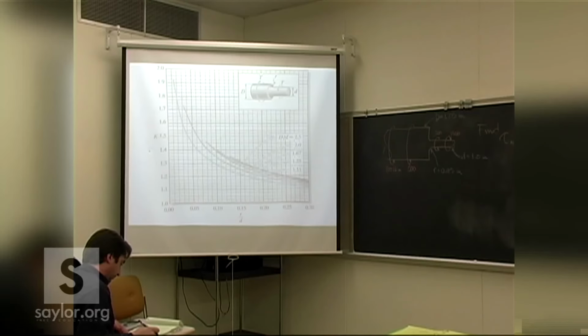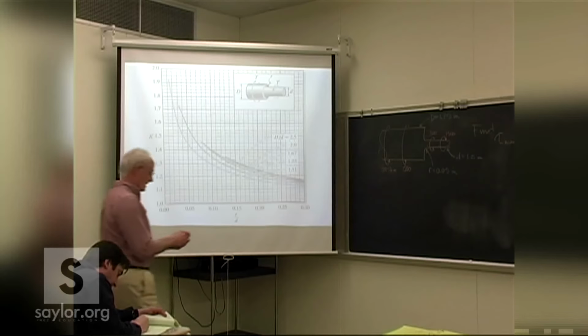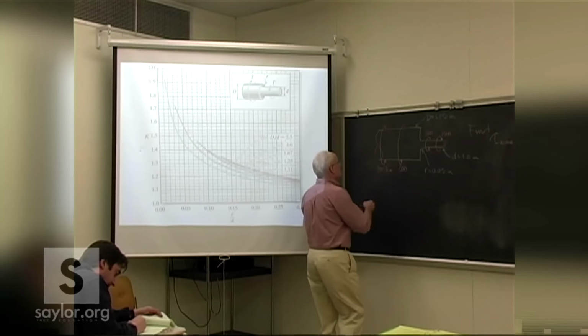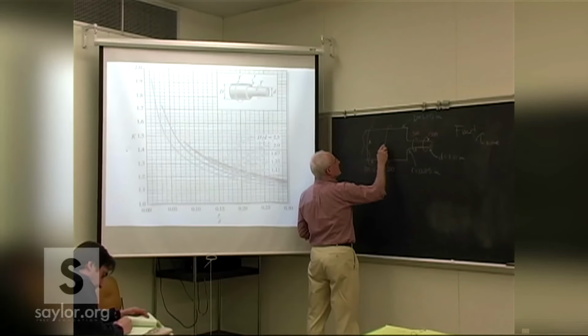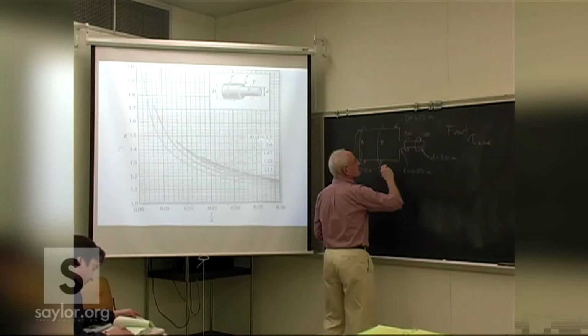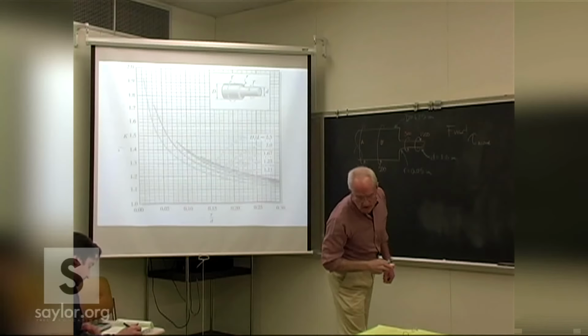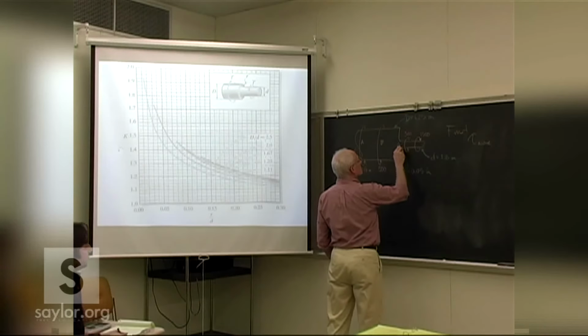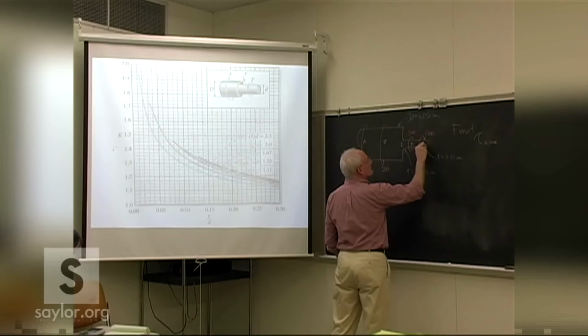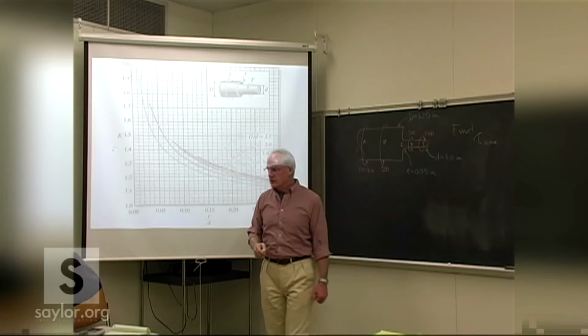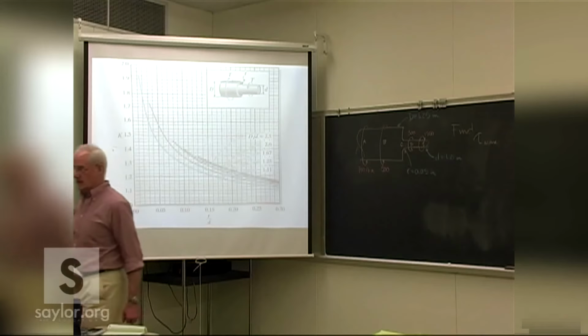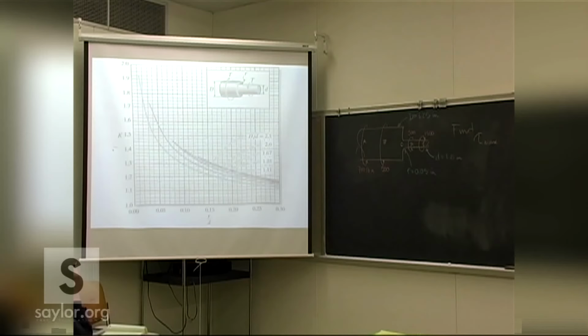So you need to find the maximum shear stress. Maybe label the different regions. The shear stress changes in every one of those regions because the load changes, and the radius changes.